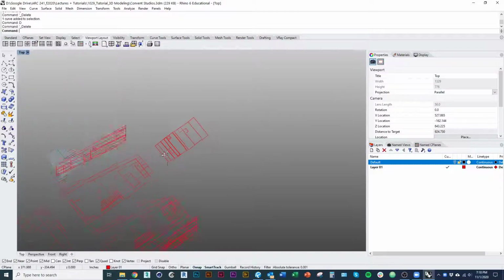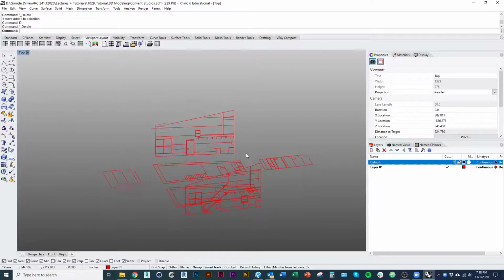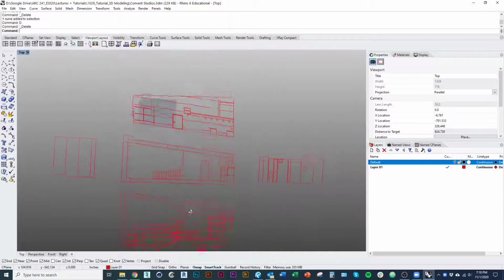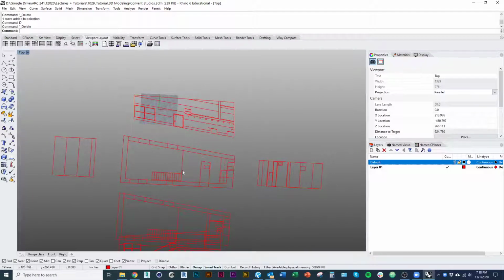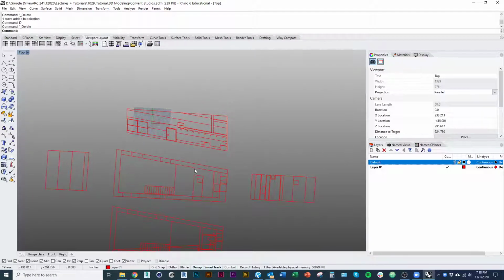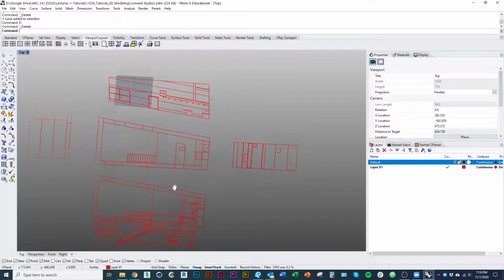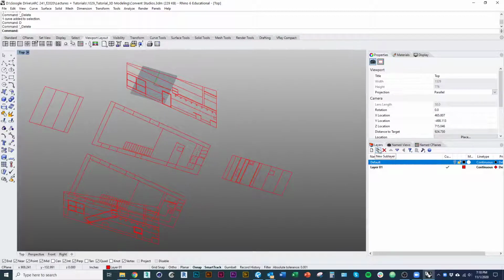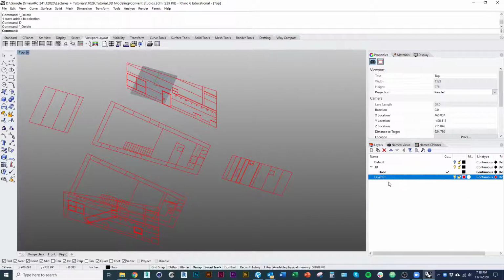That's going to make it a lot easier, because this one's lined up to my drawing, basically. So this one's oriented to that tilted wall, and this one's oriented to the straight wall. It's a little easier to work from. Okay, so I'm going to make a new set of layers, and the first thing I'm going to do is make a floor. Now, I think it's important actually, before I even do that, to make a 3D layer. I'm going to put everything 3D on there. I'm going to put everything 2D on a separate layer. These are my drawings.